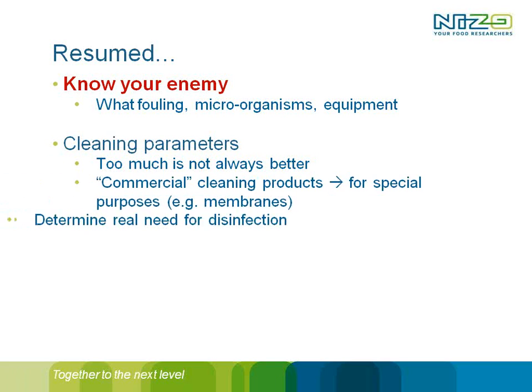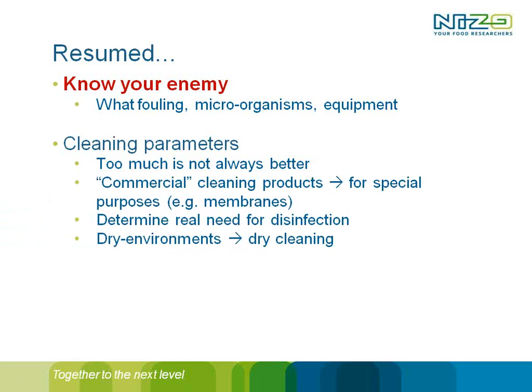If you talk about the cleaning parameters, as Arjen told, too much is not always better. Adding more caustic or alkaline is not always a better solution. Commercial cleaning products are good for special purposes like membranes. You can use them in other situations as well. It's a cost issue, and you have to decide for yourself whether you want to use them or whether you stick to regular alkaline or acid.